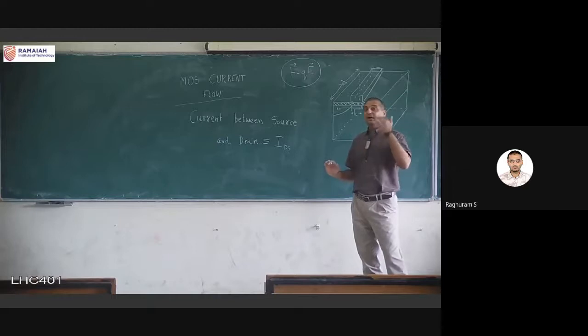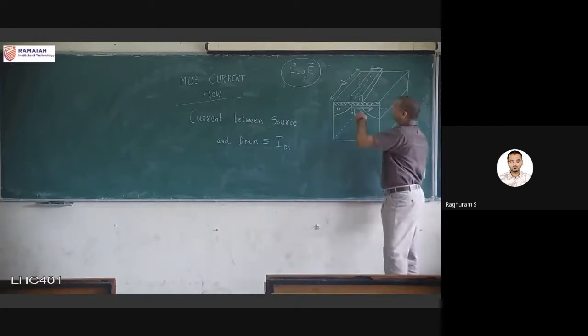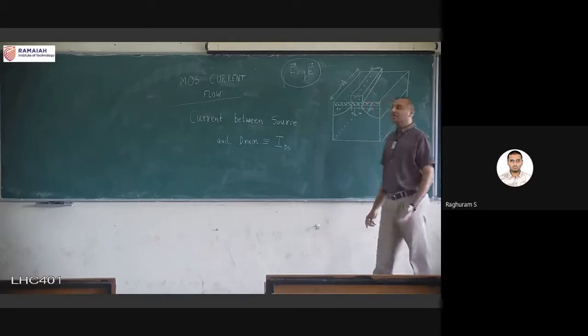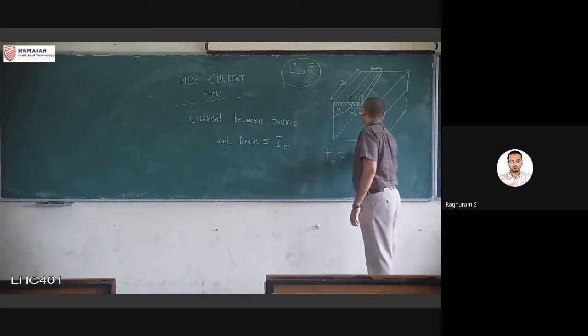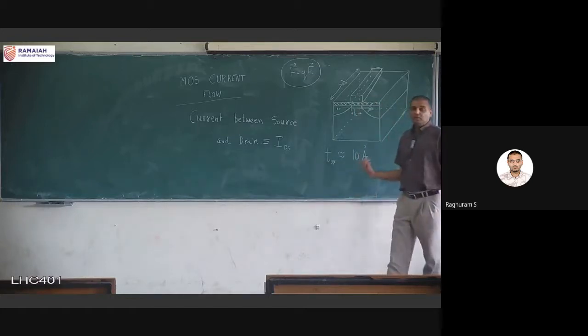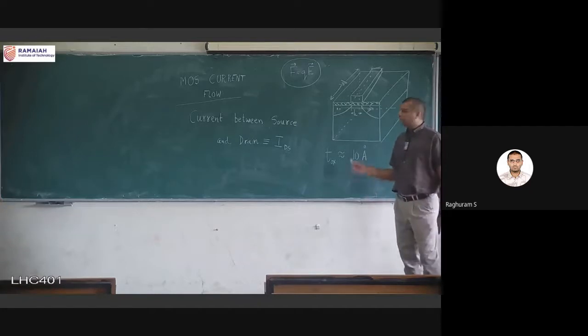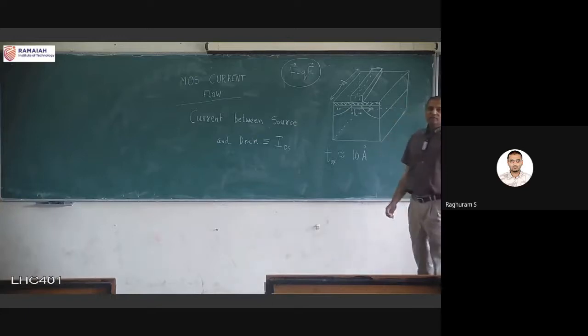If you go for some higher level course in VLSI, or even during the lab, as you will see, there are leakage currents. So we said that this oxide is thin oxide, right? Thin oxide means, you can ask, how thin is it? What is the value? The value can be very small, Tox. It can be very, very small. It can be 10 into 10 power minus 10 meters. Angstrom is generally used sometimes for this oxide, because we are at a very, very small level. Why nanometer is not used, why angstrom is used, that again is largely historic, because earlier on they were measuring in terms of the wavelength of light. So we will still continue with angstrom for oxide thickness, but this is the example of how thin this is.